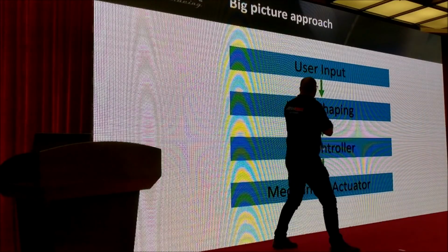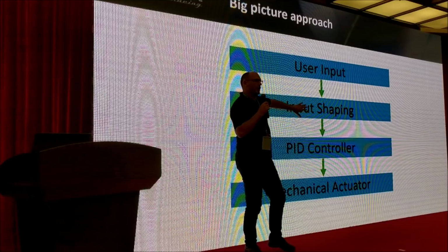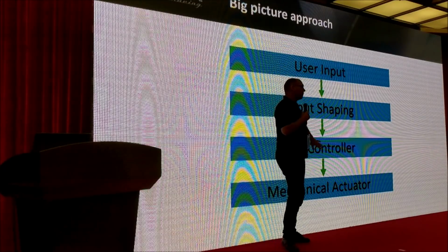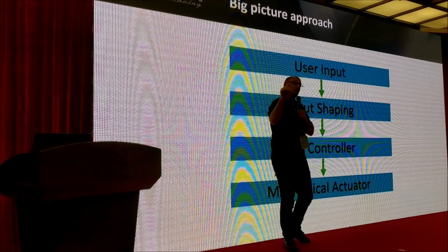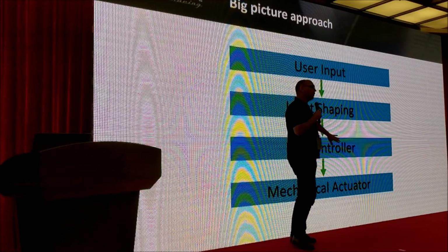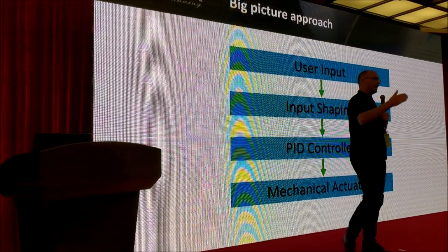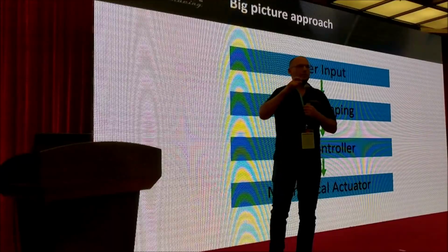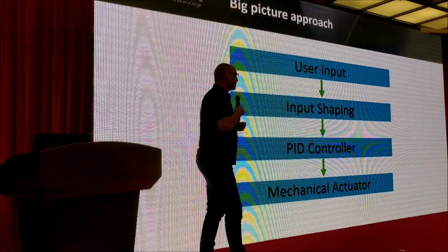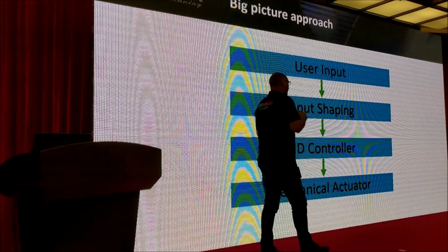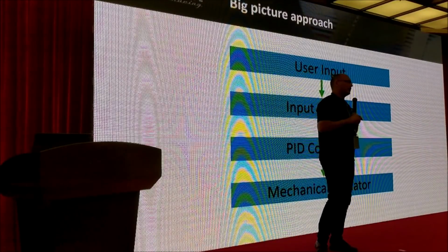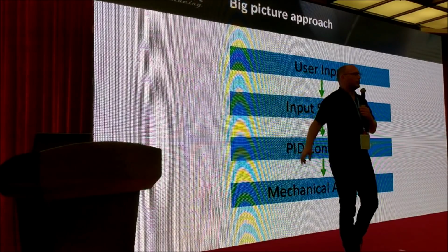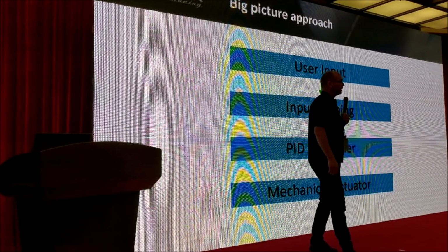And what this does is this knows what that quad is capable of, and so when it commands the PID controller and the feed forward terms, it does so in a way that it knows that the aircraft can actually handle. And in that way, it keeps those error terms small, and it ensures that the aircraft does not become unsettled and does not get into a point where the I terms are building up and the output of the motors are being saturated heavily.